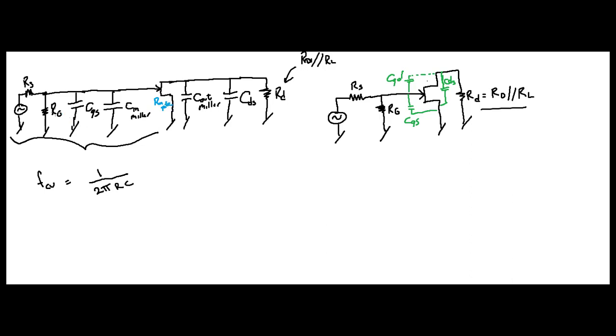You're going to have right here resistance, RG, and you're also going to have RS. Now look, the trick is to find the resistance across the leads of the capacitors. So if you Thevenize this, that means you make a short out of your source right here. You can basically redraw this below, and that's what I'm going to do now.